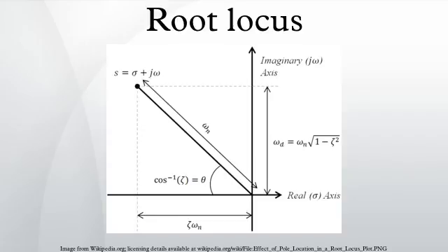A root locus plot will be all those points in the S-plane where G(s)H(s) = -1 for any value of k. The factoring of k and the use of simple monomials means the evaluation of the rational polynomial can be done with vector techniques that add or subtract angles and multiply or divide magnitudes.